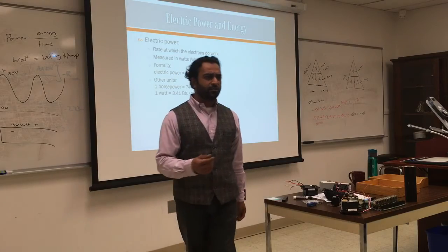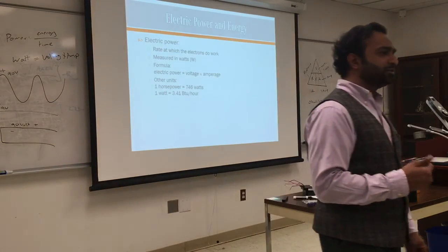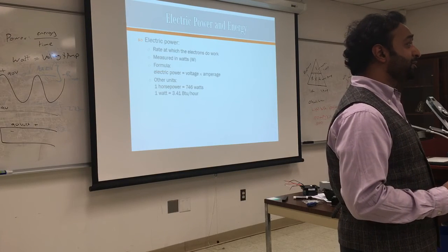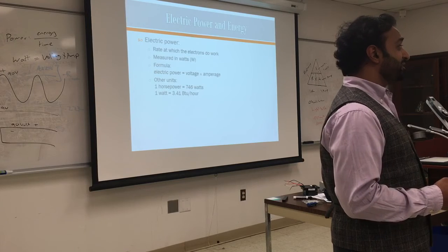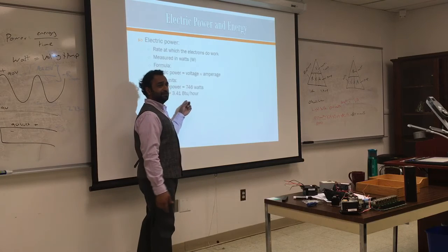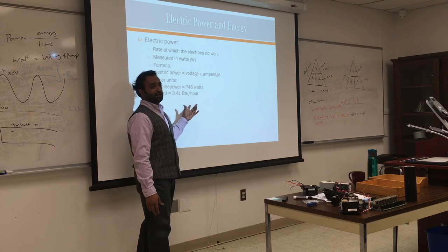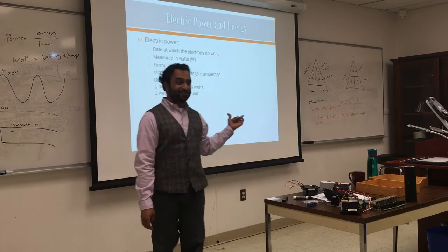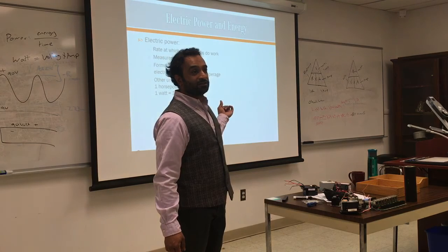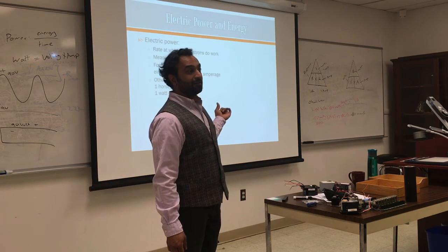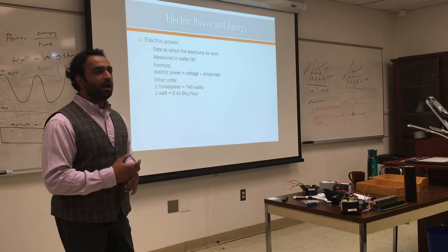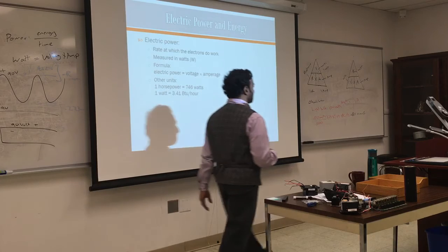Do you think the conversion from electricity to heat is efficient or not? Actually, it's pretty efficient. It's the most efficient way, 95% efficient. So you put in 1 watt, you get almost 3.3 BTU per hour. That's not the problem. The problem is it's expensive. It adds up, and you're not going to heat the room with 1 watt. It's going to be at least 2,000 watts. So it's a lot. I will do some math to get a concept of why things cost so much money, and why it matters to cut power here and there.